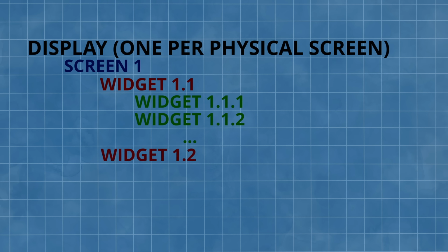Just below this are screens, which are the base of the tree on which you're going to stack elements, or widgets as LVGL calls them. There are dozens of widgets, including labels, buttons, message boxes, menus, tables, and so forth. Once you've created one or more screens, you add widgets to them, and then you can add widgets to those widgets, and so on, in a parent-child structure.